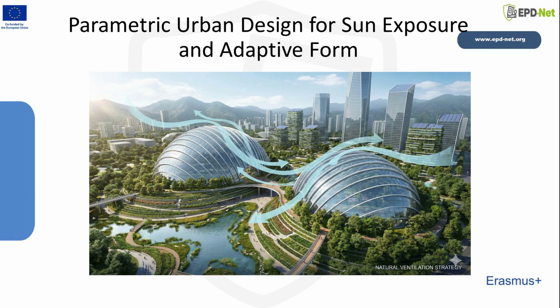Parametric tools allow performance parameters, such as differential sun exposure or wind loads, to drive geometric design. For instance, a sun exposure map imported from an environmental analysis tool can deliver data input for component differentiation. The parametric designer can set up a dependency rule: the higher the sun exposure of a surface patch, the smaller the opening of the facade component at that location, thus optimizing daylight penetration and minimizing solar gain. The resultant facade articulation becomes a representation of the surface's differential exposure to the sun.